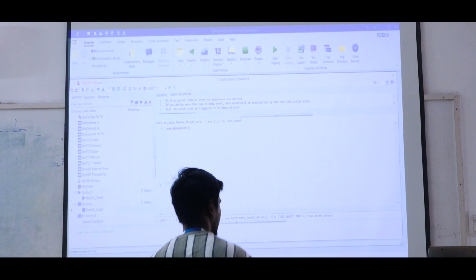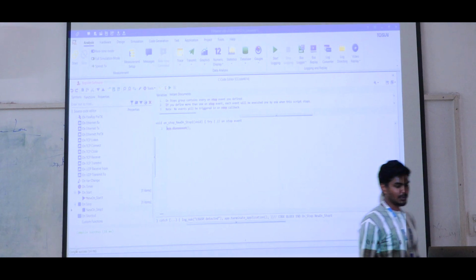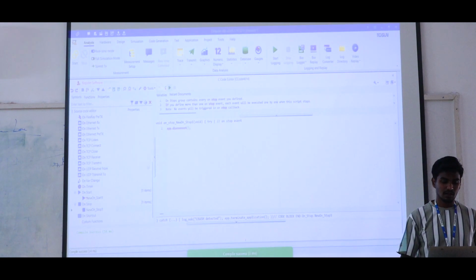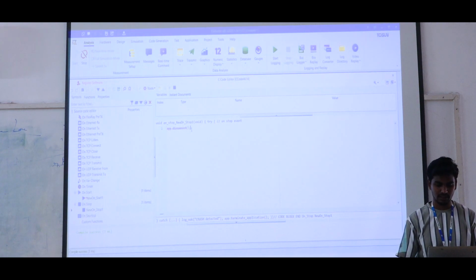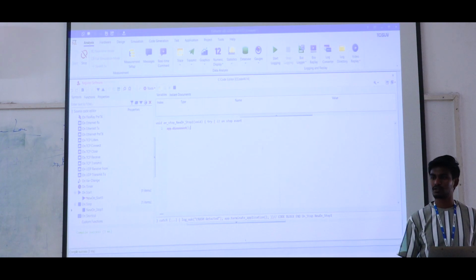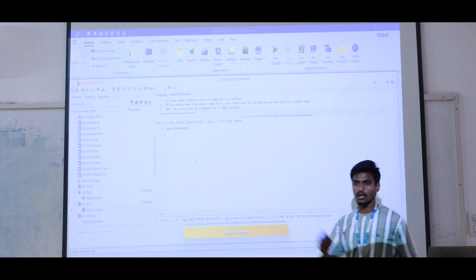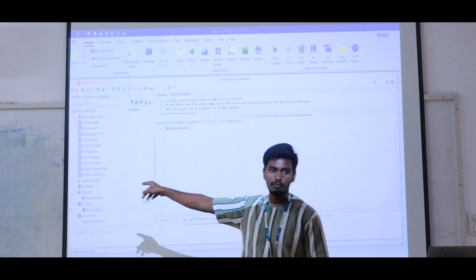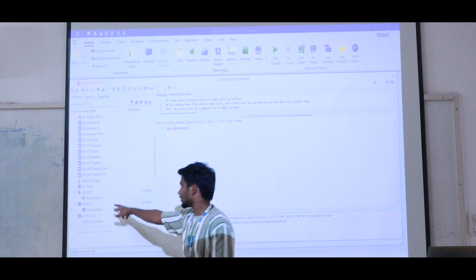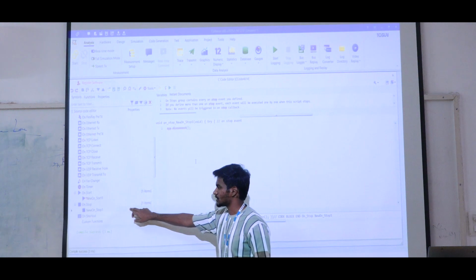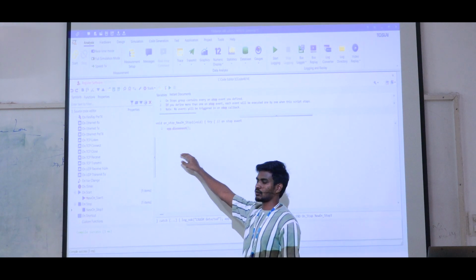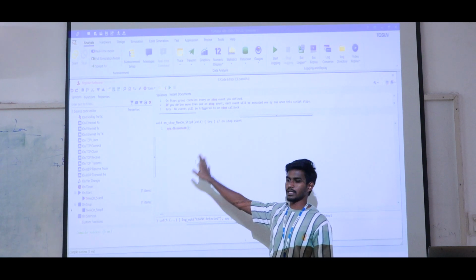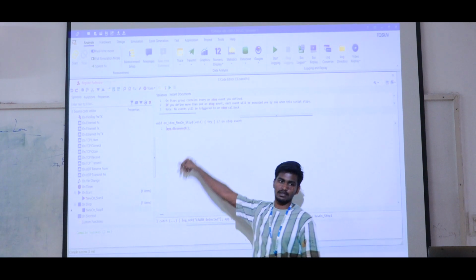So before going to the editing session in our scripting, if the script is running, please ensure that the script is stopped, because if you are typing or editing anything it will not work. So before going to the editing session in the script, please stop the script here. Okay. Just stop the script. Afterwards go to on stop, right click, add on stop, and then click this new on stop. Type app.disconnect. You will get the completion using the enter button, using open close brackets, semicolon.